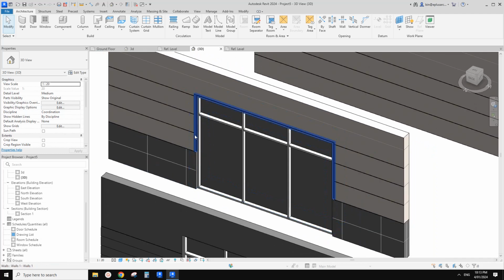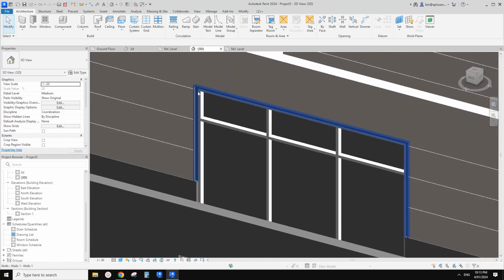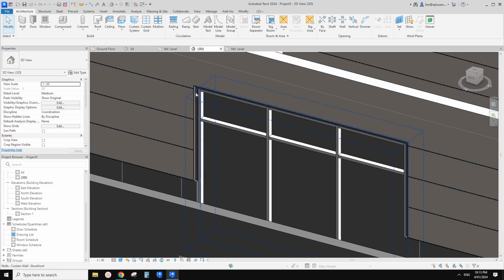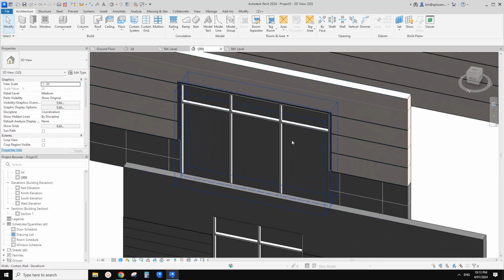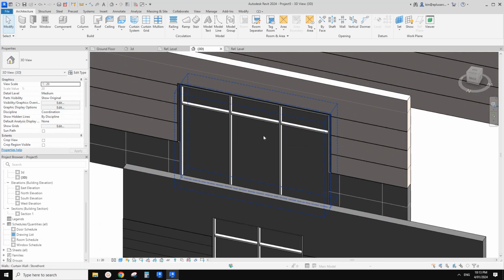Otherwise, you need to create a vertical and a horizontal, and sometimes it won't join properly in this corner. Also, it won't automatically, or at least semi-automatically, adjust to suit your new door size or window size.